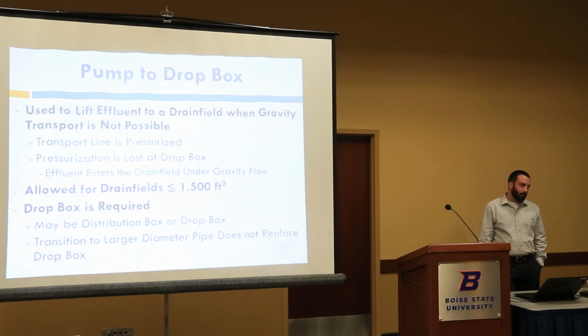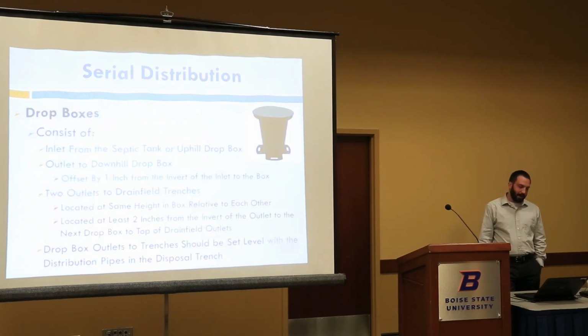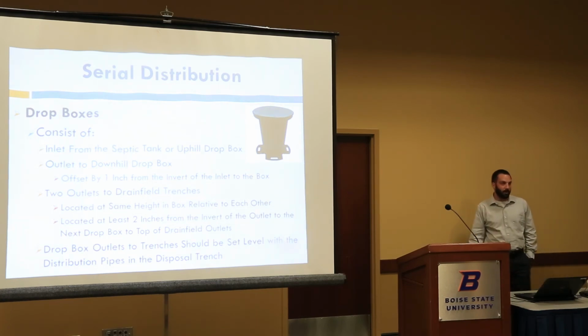What size drop boxes? There's really no list of approved drop boxes or distribution boxes in the state. They just have to be compatible with wastewater. So usually it's precast concrete or poly plastic, basically wastewater grade plastic. I do have an example way back this way. That's a plastic one that could be used as a drop box or a distribution box. You probably can't see it, but there's about 6 different inlet or outlet heights on that thing along the sides, so you can set those elevation differences in the drop box.